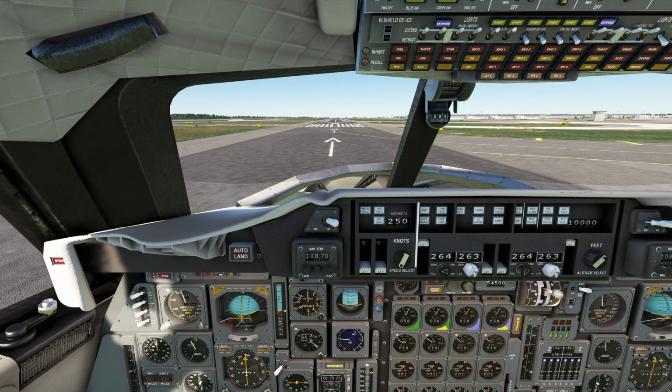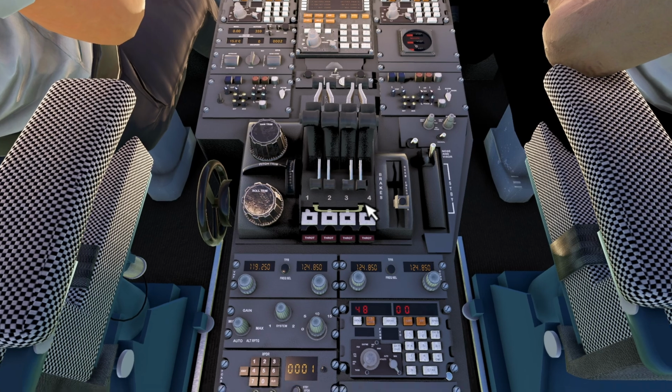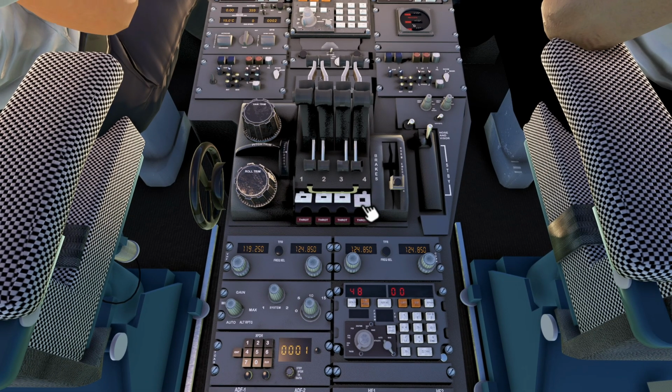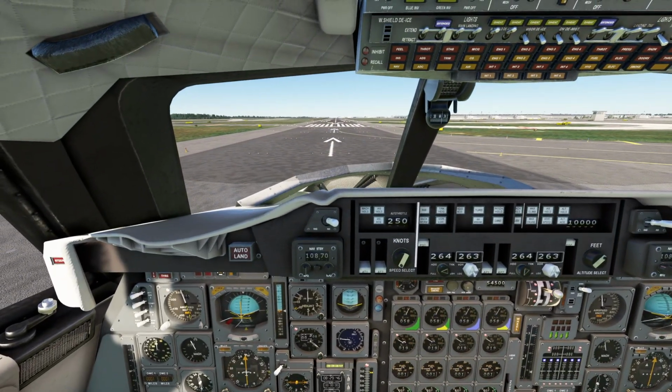We are ready for departure, runway 26 right at Paris Charles de Gaulle. Autopilot is programmed, visor is down, lights are set. We're going to pre-engage our afterburners so we can use them if we go to full power. Parking brake release. We start the timer to have 30 seconds that we need to turn off again because of noise.